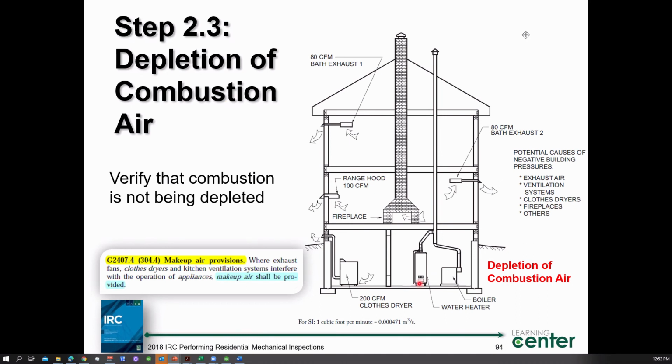You follow? I've run into this when I was a contractor. I've run into this all the time. If you don't have enough combustion air or makeup air, what's happening? You're getting a negative effect. You're drawing downward, right? The products of combustion are spilling over the draft hood.